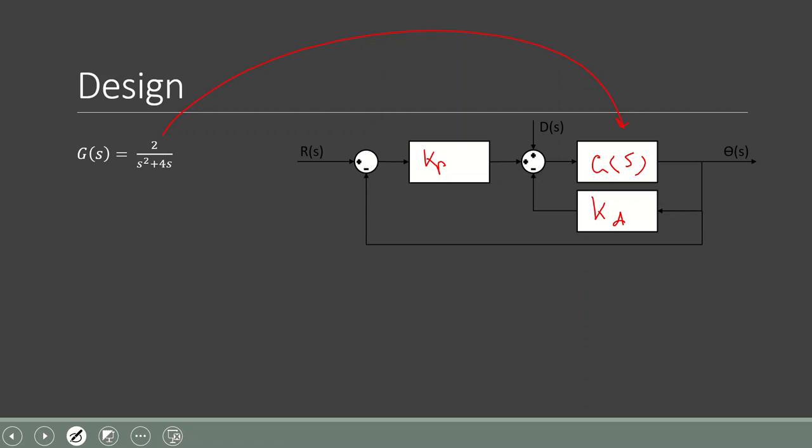And we also decided to say that our disturbance would be 0 because we're in a fairly isolated room, and we're already accounting for the air friction in our original model with the damper. So taking all this into account, this gives us a final transfer function.